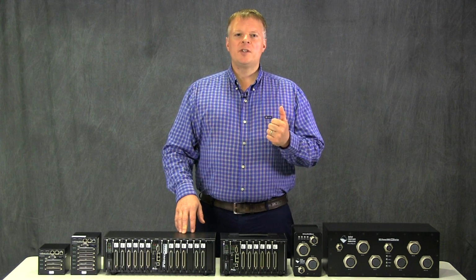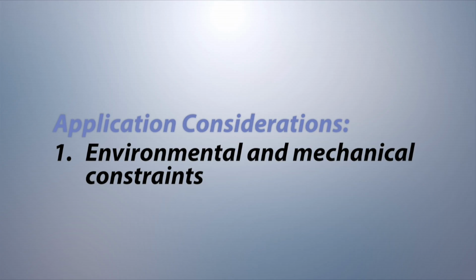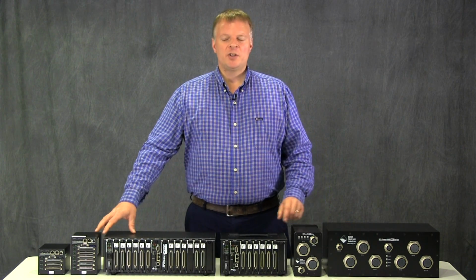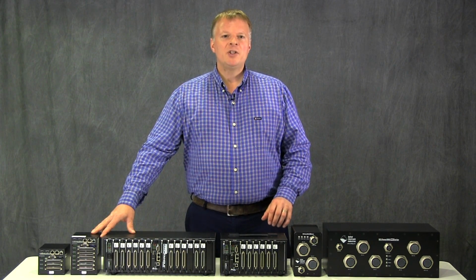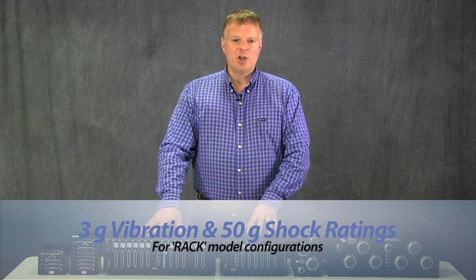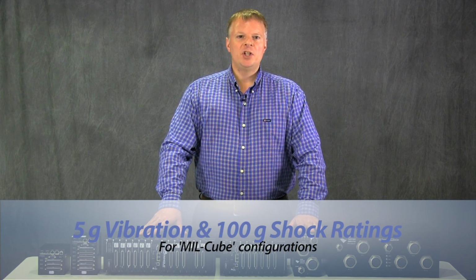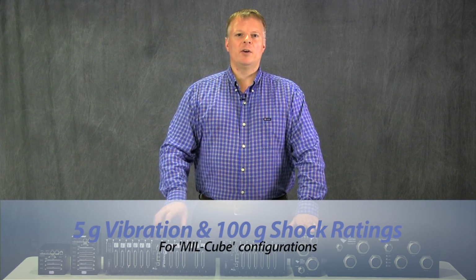When deciding on the proper configuration for your application, there are several considerations. The first thing to consider might be the environmental or mechanical constraints of your application. Will your device need to be operating under laboratory conditions or in a harsher environment? In other words, how rugged does your chassis need to be? While all UEI chassis configurations are rugged in their construction, they range in their shock and vibration ratings from 3G vibration and 50G shock for the rack models to 5G vibration and 100G shock for the mill series cube configuration.